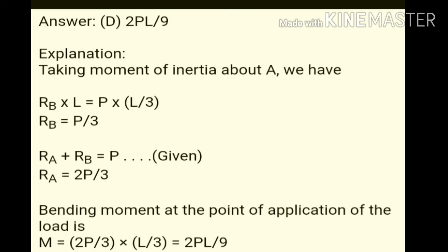So the bending moment will be force into distance, that means RA into L by 3, that is equal to 2P by 3 into L by 3, that is equal to 2PL by 9. So the answer is D, 2PL by 9.